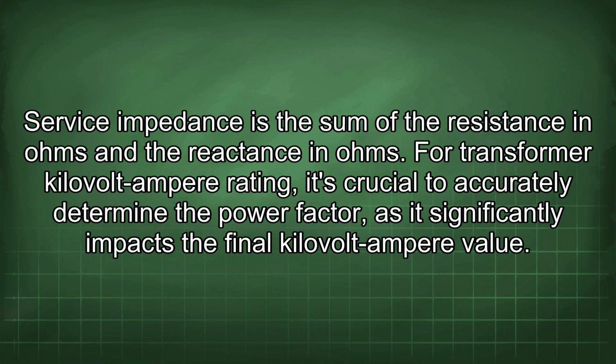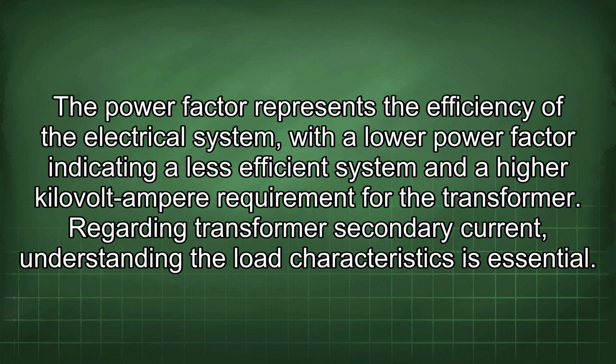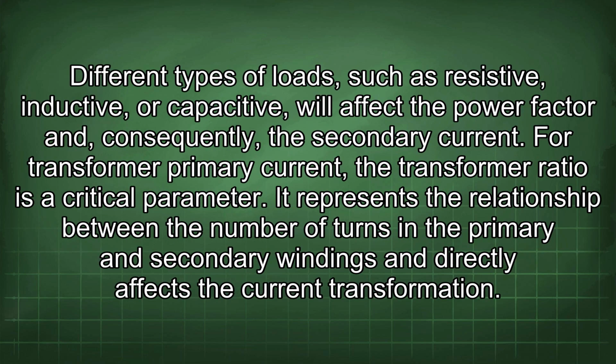For transformer kilovolt-ampere rating, it's crucial to accurately determine the power factor, as it significantly impacts the final kilovolt-ampere value. The power factor represents the efficiency of the electrical system, with a lower power factor indicating a less efficient system and a higher kilovolt-ampere requirement for the transformer. Regarding transformer secondary current, understanding the load characteristics is essential. Different types of loads, such as resistive, inductive, or capacitive, will affect the power factor and, consequently, the secondary current.